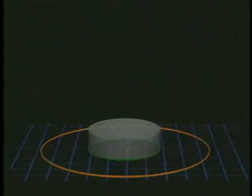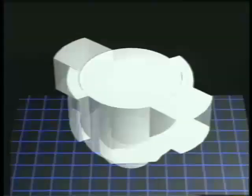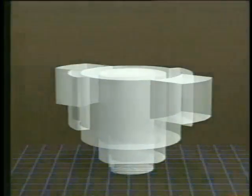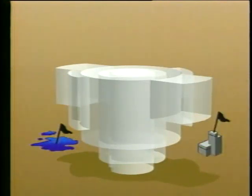A clearance from ATC is required before you enter Class B airspace. Your initial call-up should be outside of the Class B boundary and over a designated visual checkpoint. These points are shown on aeronautical charts and will be covered in depth in the section on charts.